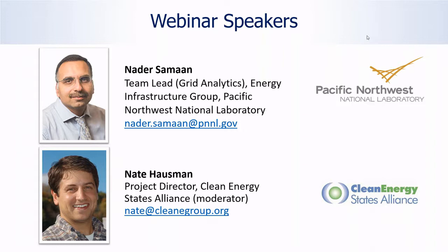So I'm assuming the question is saying the PV is absorbing reactive power. Is that correct? Absorbing or delivering? Absorbing. Okay, absorbing. So yes, here the PV is acting as an inductive load, absorbing reactive power, and yes, that will increase the VAR flowing back from transmission to distribution. So it's kind of a trade-off. Yes, you'll increase losses, but in return, you are maintaining your voltage level within the required boundary.